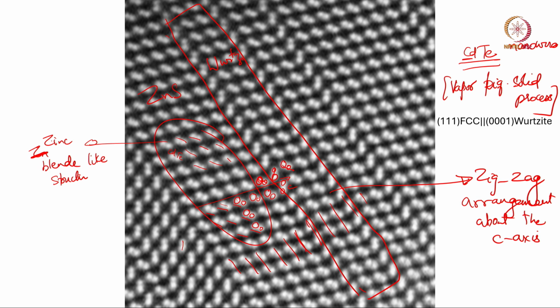If I have similar stability of 2 different phases in a material, and they both can be coherent just like zinc blende and Wurtzite, the only difference between them is how you rotate the tetrahedra. In Wurtzite, every alternate layer you are rotating the tetrahedra by 180 degrees, but that is okay. Both of them are similar in energy, and it is a very small energy penalty that I have to spend in going from zinc blende to Wurtzite. So, both of them will form, right.